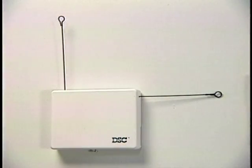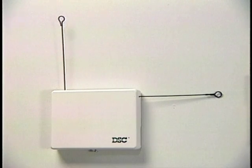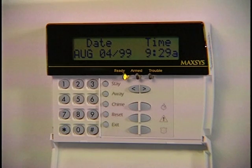Wire the PC4164 wireless receiver to the 4-wire COM bus. Notice the antenna arrangement. It is very important that the antennas are installed with one up and one out in opposite corners. This will maximize the receiver's ability to receive wireless transmissions. The PC4164 must be enrolled to the system before it will function.